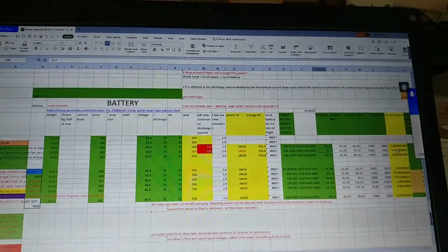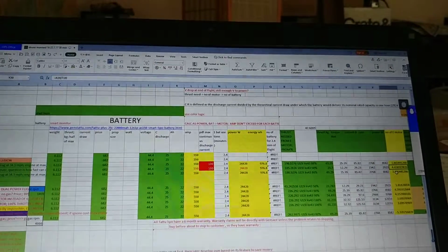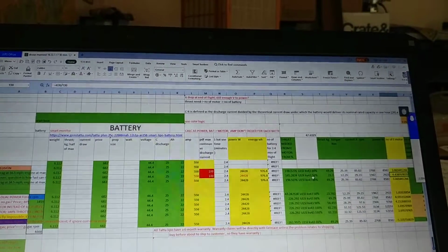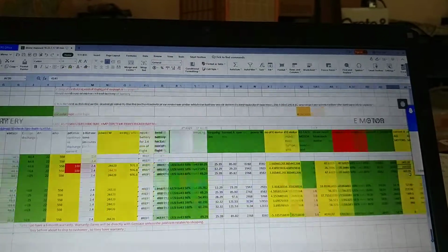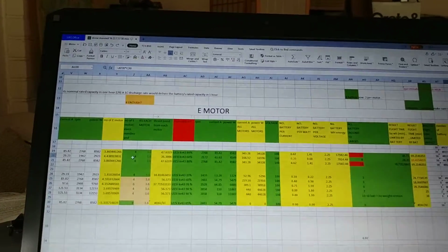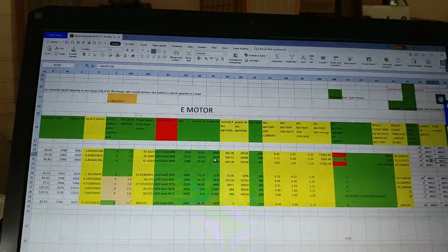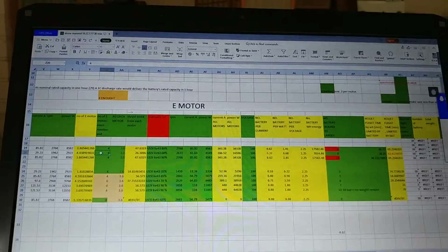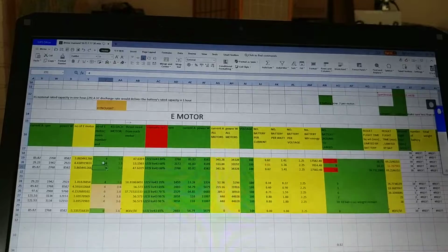So I need 4 motors when each motor is spinning at 50% throttle, meaning I manually enter, let's move over here. Then I manually enter 4 motors and they'll be spinning at 60%, then I'll be able to lift my craft. So we can put in more motors, and then the thrust required becomes less, because if you have more motors, each motor needs to work less.